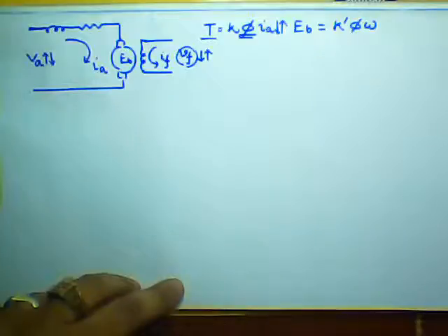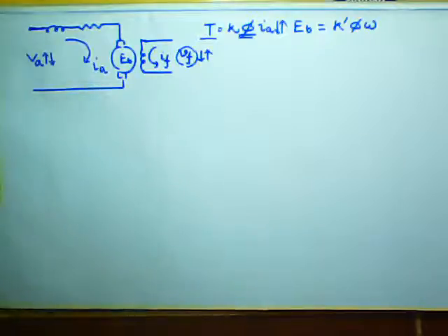The total current which is drawn at a certain instant, you cannot tell from that amount of current how much is producing the torque of the machine and how much is producing the flux of the machine, because it is a vector summation, and that is entirely dependent on the instantaneous rotor position.